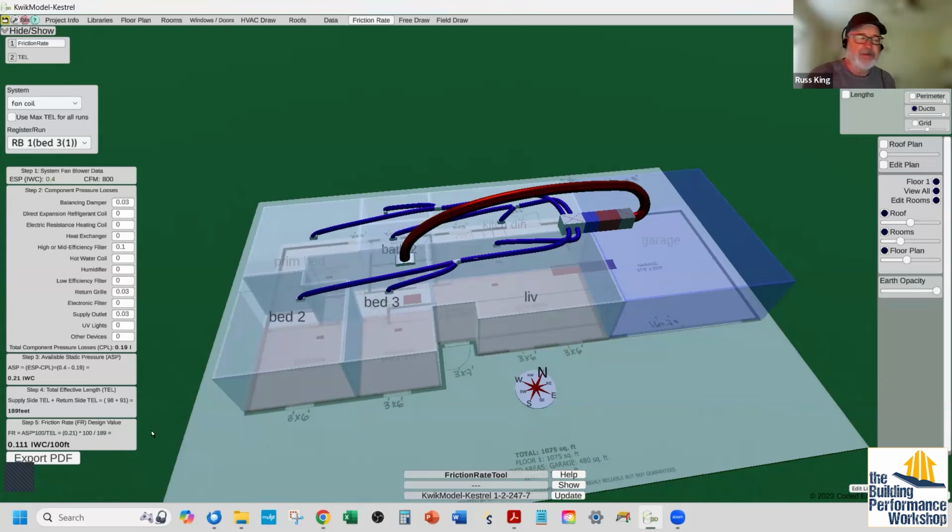Put in a smaller duct size and you won't have to put a damper on there. Now, there is a statement in there that says there's no such thing as a self-balancing system. I would argue that you can get close enough just by sizing ducts. If you're using odd size ducts, there's a lot of people who don't use odd size ducts. They can't even buy 5s, 7s, and 9s at their local distributor. They have to custom order 5-inch, 7-inch, and 9-inch ducts.